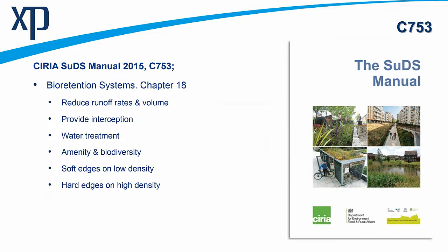Well, they can certainly help us to reduce those runoff rates. They can help us to reduce the runoff volume. They provide excellent interception, as I already mentioned, of those regular rainfall events where we can intercept the runoff for those less than 5 millimeter conditions, and it'll be handled within the basin itself, with nothing possibly discharged into the positive drainage system under the ground.